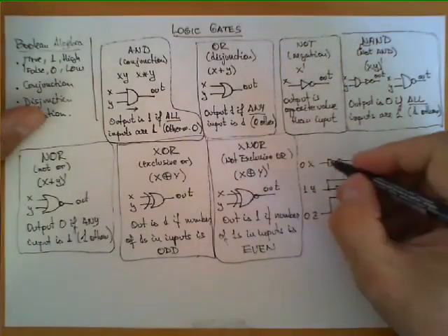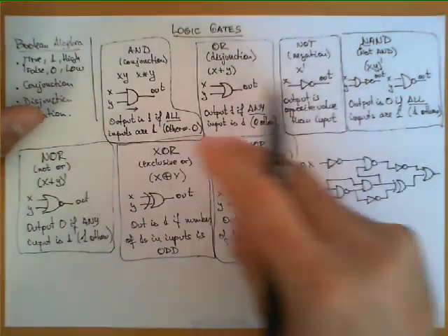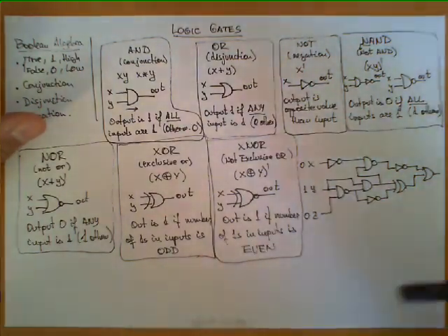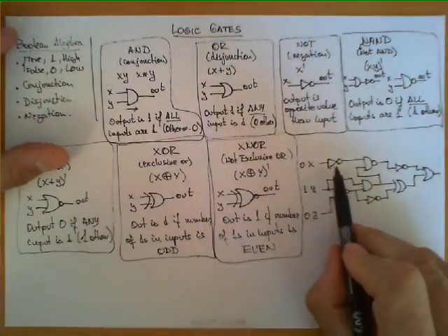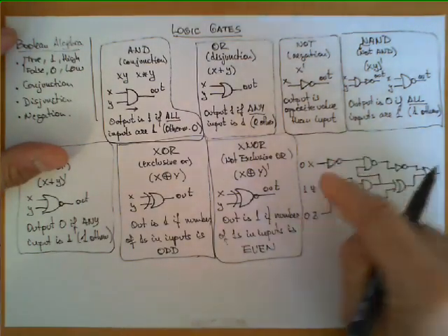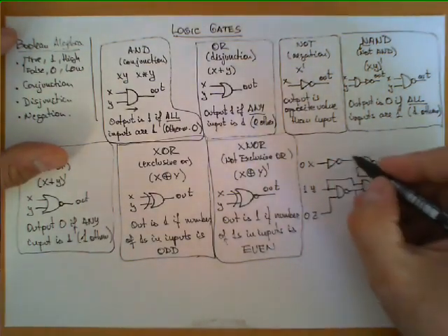Now the only thing we need to do is apply the rules we've seen here, and remember that the direction of the signals is always going towards the right. So this is very simple. This is an inverter and is directly connected to X. We assume that X is equal to 0, therefore here in this wire we have a 1.